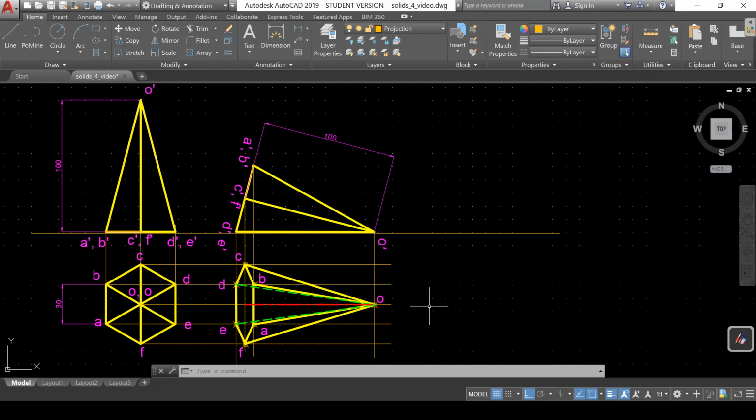Now these two steps are solved here. We are going to construct the third step now. In this case, third step, we will tilt this top view from the second step such that DE is inclined at 45 degrees to XY. So let us draw the line at 45 degrees to XY projection layer.